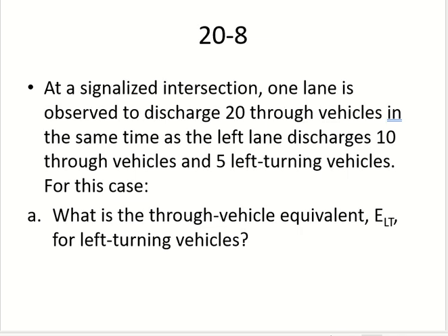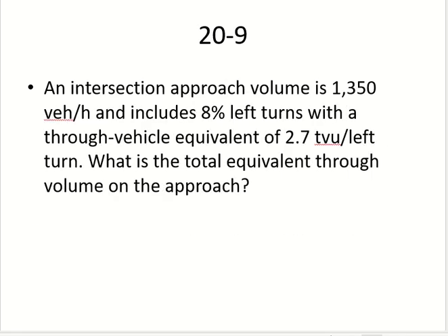In the same way, you can do it for different combinations. So in this example, again a very small one, the equivalency factor is 2.7. According to the intersection geometry, the equivalency factor for left turning is 2.7.